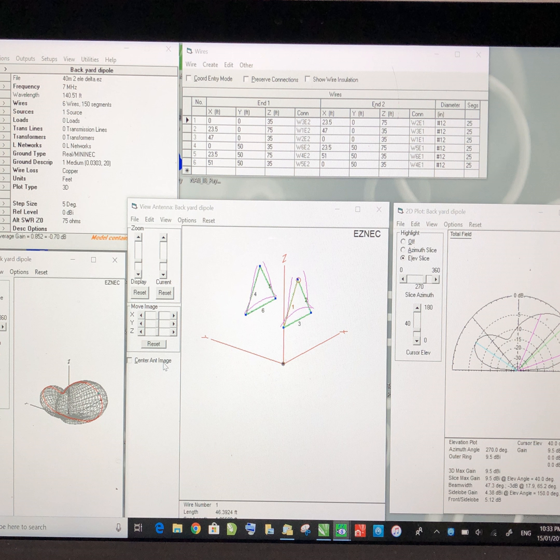I've uncovered these after sometimes several years, and if you use self-amalgamating rubberized tape first and then a layer of vinyl tape over the top of that, really not much moisture will get in there and the connection stays very good. So you don't have to solder those connections at the center between the coax and the wire, but it is important you try and stop the moisture from getting in there. There's various ways of doing this, and we'll probably cover some of this in a future episode.